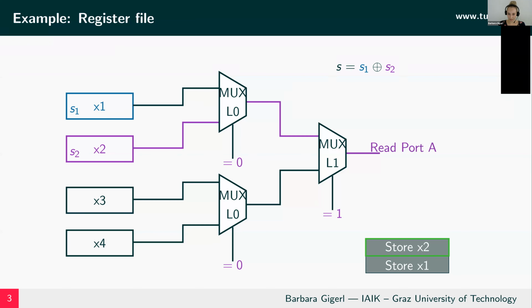And what happens now is that this multiplexer here switches the select signal from 0 to 1, which leads to the output of the multiplexer switching from the previous value to the new. And we have a transition from one share to another, which means we have a leak in our program. You might argue that this is a rather obvious case because you're accessing your shares in 2 consecutive cycles, but there are cases in which it's not that obvious.